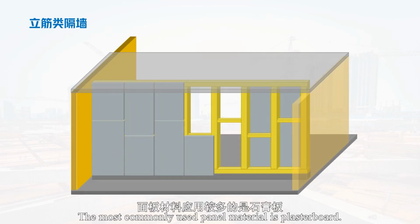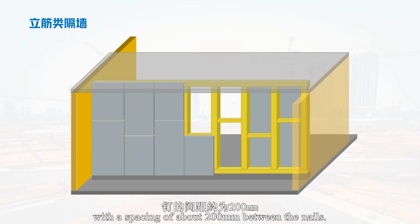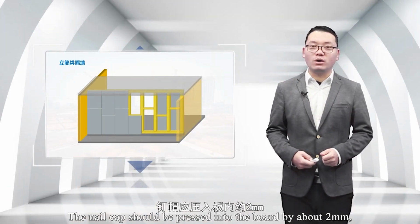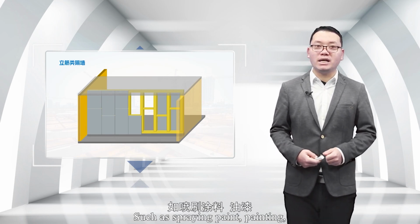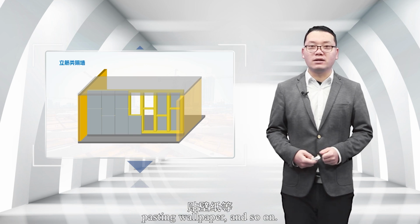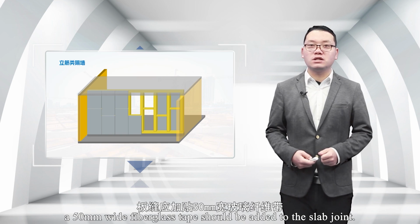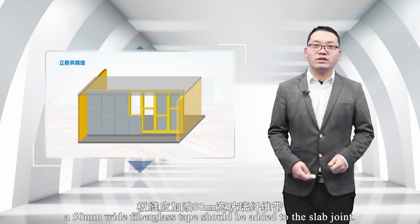The most commonly used panel material is plasterboard. The plasterboard is connected to the keel with self-tapping screws, with a spacing of about 200 mm between the nails. The nail cap should be pressed into the board by about 2 mm, and the surface of the plasterboard can be decorated, such as spraying paint, painting, pasting wallpaper, and so on. To avoid cracking, a 50 mm wide fiberglass tape should be added to the slab joint.